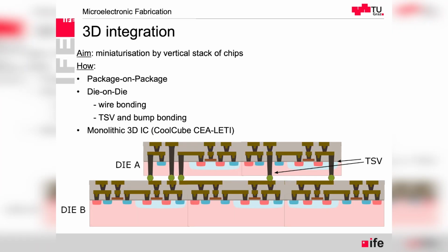So in technology scaling, the trend of reducing the transistor size, we already see it will have its limits, and it's a continuous discussion what comes next. What's already started to come is 3D integration, and that's something that we have observed over the last at least two decades in different forms: stacking two packages on top of each other to start with, then stacking dies, so one silicon die on top of another.